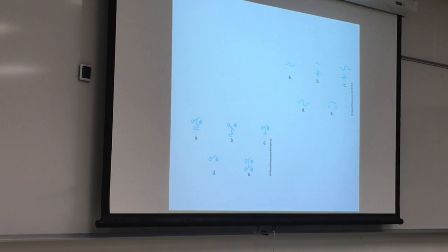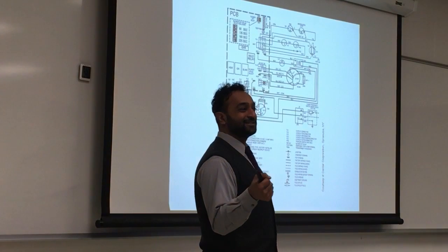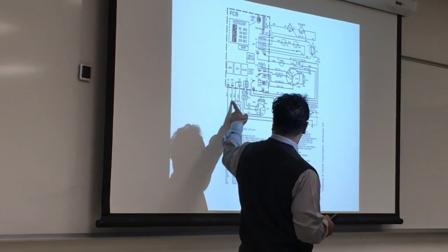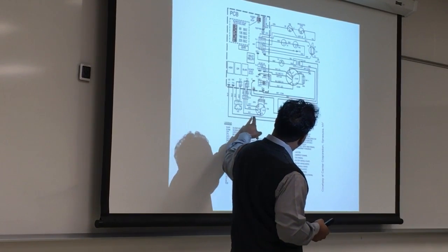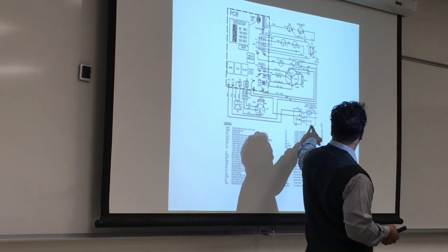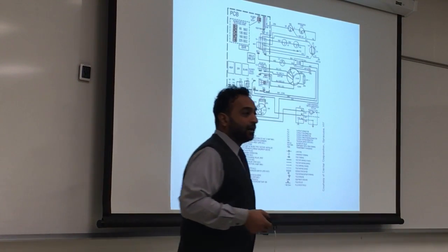So the first thing is to find where you are. How do I find where I am now? I have my plug. That's my line voltage. I'll find my line voltage and trace my way out. My line voltage is here, coming all the way from the wall. This is my switching relay, ground, black and white. This is my line voltage, and I keep it going.